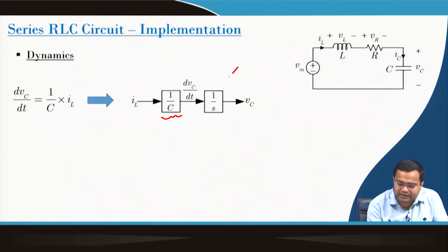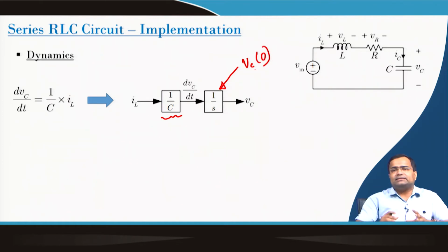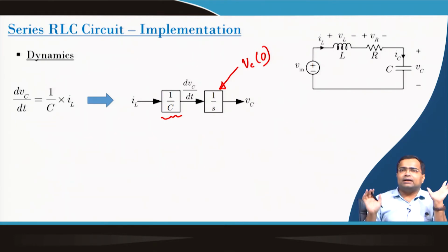Similarly, we can define the initial condition of the capacitor voltage inside this integrator. Inside the integrator, we can plug in Vc0 symbolically and define it outside.